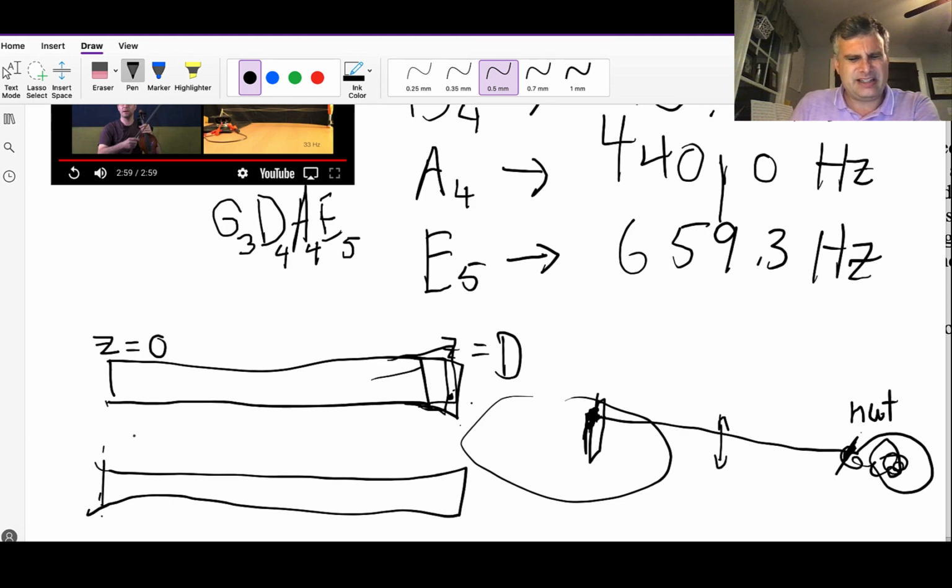Well, let's take a look at voltage on the transmission line. Voltage does not go to 0 at the end of the line. If you have a standing wave, it'll actually reach a maximum at an open circuit. Because, if you remember your formulas from class, the reflection coefficient gamma for an open circuit is +1. 100% of the waveform is reflected because it has nowhere to go. The energy cannot dump into anything, and it's a +1, meaning that there's no phase change. But that's actually for voltage, keep in mind.